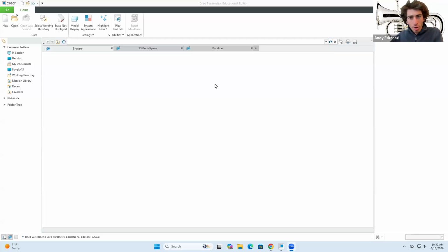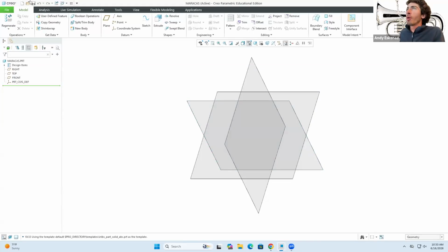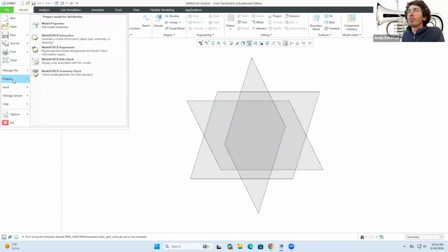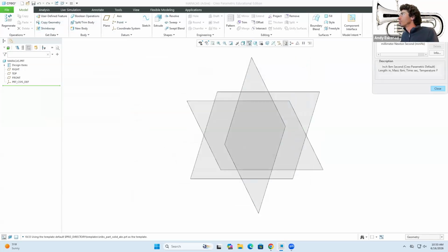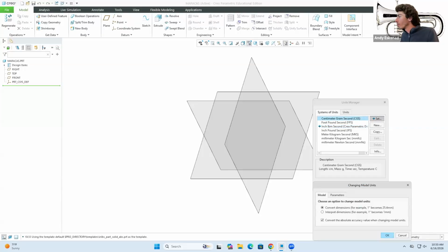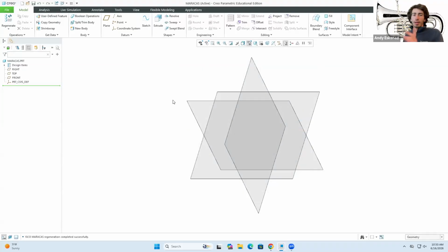Alright, now we're back in Creo, so we can get started with today's session. I'm going to start by doing a demo of the different commands that we'll be employing today, and then I'll get into today's projects. As usual, we go to new, and I go to part. I will already call this one maracas, because that's what we're going to start with after our demo. We click okay, and now we're in our space, and as always, I go to prepare, model properties, units, and change these. Okay, close.